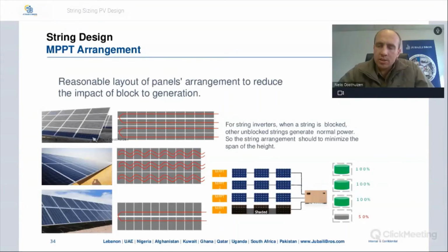But then also it's actually recommended to use your panels in a landscape orientation due to the diodes. So typically a panel has got 3 diodes built into it, split evenly. But nowadays we also have half cell modules where it's one module, but it's almost split into 2, so you have 2 different sections.